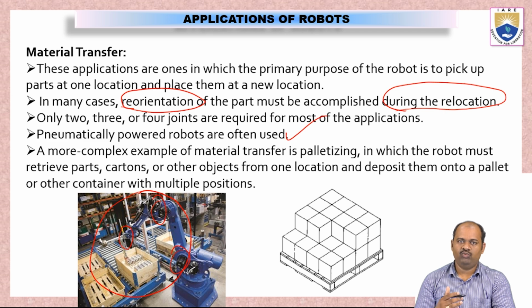It does not move the piston slowly; it immediately pushes the piston to the other end of the cylinder. So when we require this kind of motion, we can use pneumatic cylinders. Mostly in applications where material is transferred from one place to another, we can use pneumatic cylinders for moving the objects. While placing the objects, we can simply use a pneumatic cylinder because it will release the object into the crate.